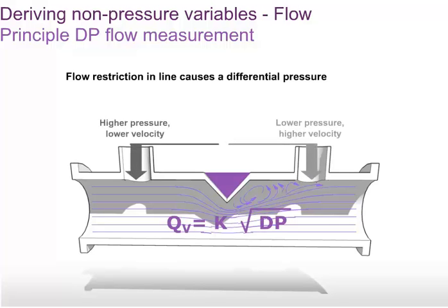The differential pressure measured by means of an obstruction in the stream is not linear with flow. To make the signal linear with flow, it is necessary to perform an arithmetic conversion by extracting the square root of the pressure differential signal. Electronic differential pressure transmitters are available with square root extraction electronics built into the instrument as standard.